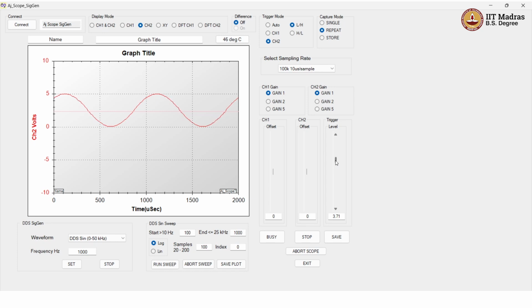Okay, so why did we go into this? This is a detour, but this is something that you have to implement. Having just an A to D converter is not enough. An A to D converter is there in your Arduino itself, right? But to implement an oscilloscope, you need to implement a robust trigger functionality. The bug I'm talking about is the following: I'm asking it to trigger, but I have set the level to be out of the range of the signal. It's a very simple bug, right? So what happens? It's not able to find the intersection. What should it tell me? It should tell me that I am not able to find the intersection, or in better words, that your trigger level is out of extent, please reset. That's all. We just have to implement that.